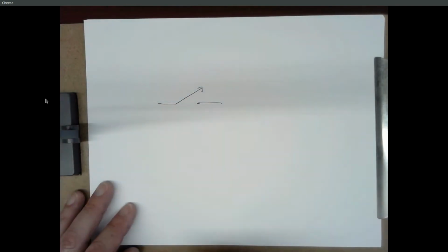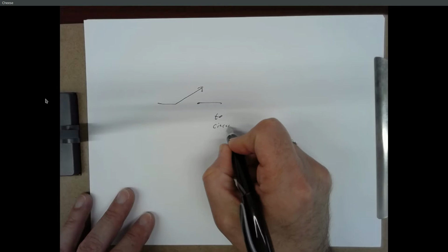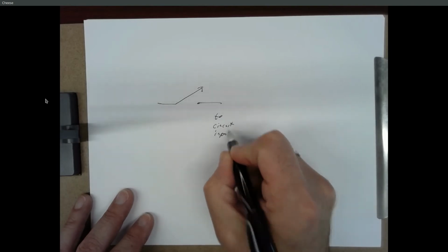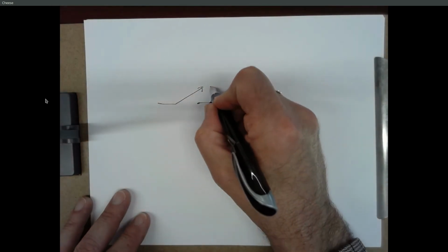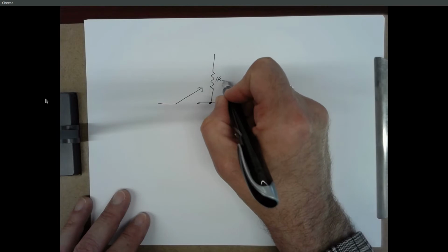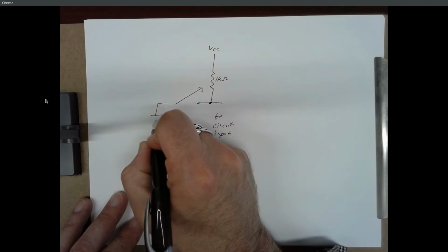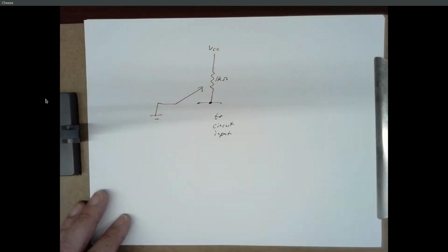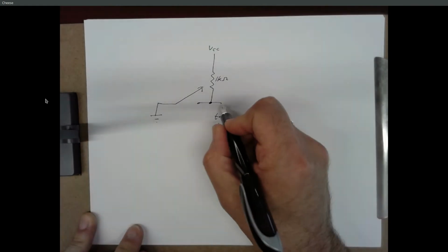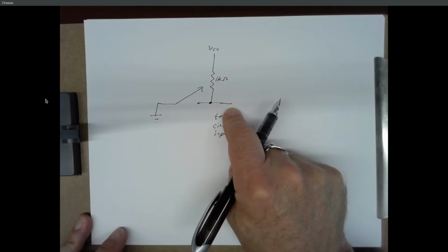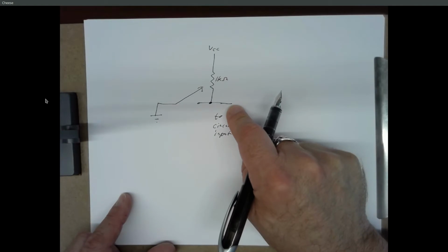So there's a symbol for a switch, right? This is going to whatever circuit, whatever input you need on the circuit. So the way you want to wire a switch is take this part that's going to the input, run it through a 1K resistor up to 5 volts VCC, and take the side that can get connected optionally through the switch and connect that to ground. That's your symbol for ground, or you can label it GND. And now this point will be at 5 volts, logic 1 normally with the switch open. If you close the switch, this will get pulled down to ground.